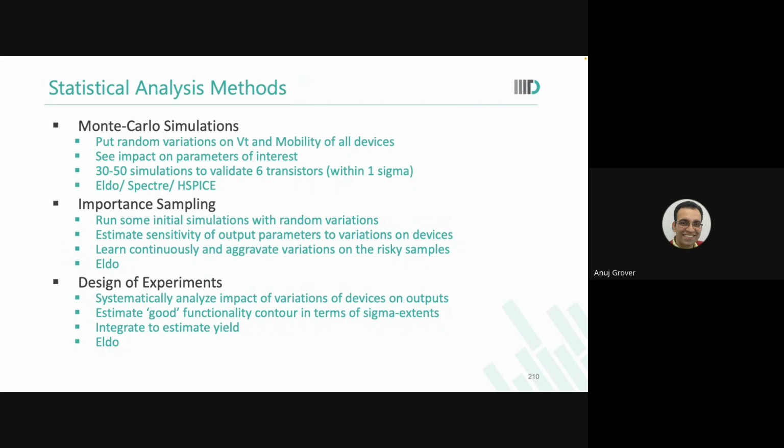Again, it's a hope because the process of picking up those variations is still random. The tool does it without really understanding the circuit. You just put in some machine learning into it. So for design verification, sample and importance based Monte Carlo was the first machine learning implementation.